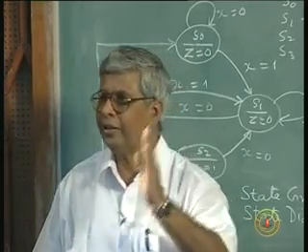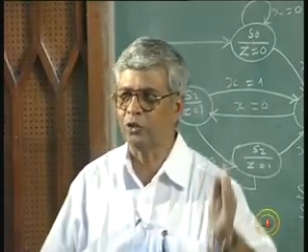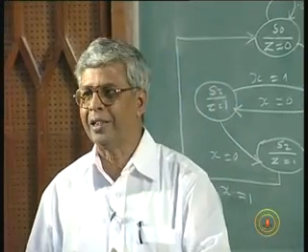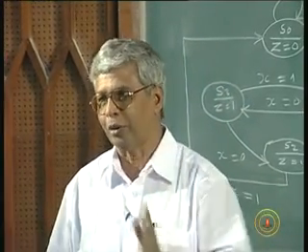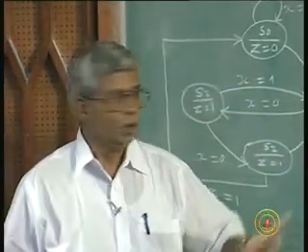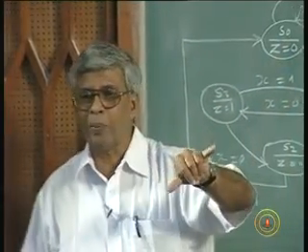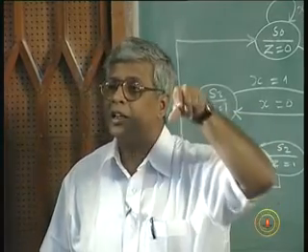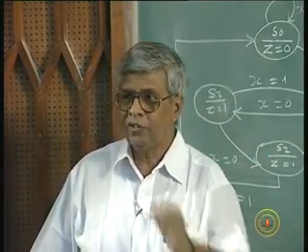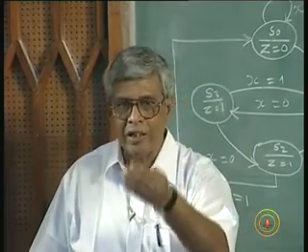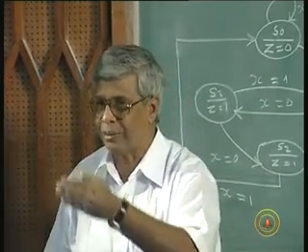And then suddenly you change your input from x equal to 0 to 1. At the next clock transition, now you have changed, so I will also move. Go to S1. So one transition corresponds to one clock period, but not necessarily every clock period if there is an external input. If there is no external input, then every transition will lead to a new state on each clock. That is the counter example I told you.